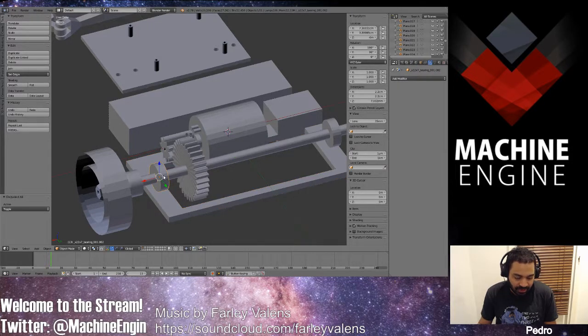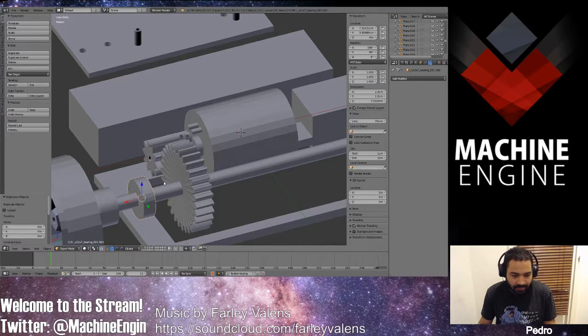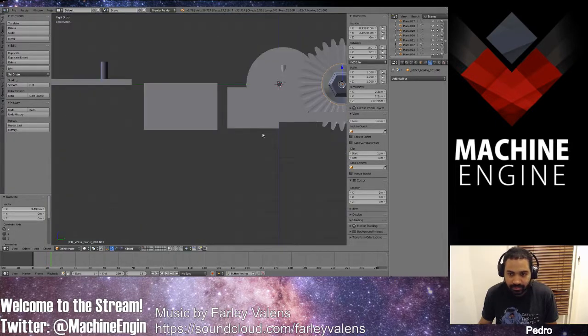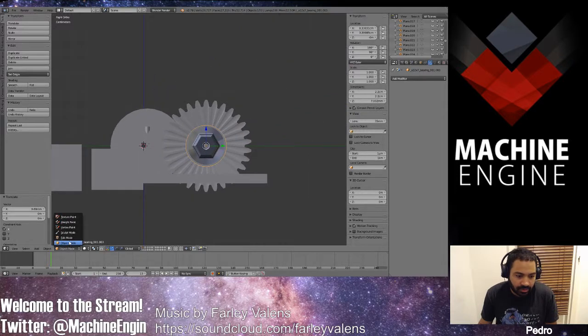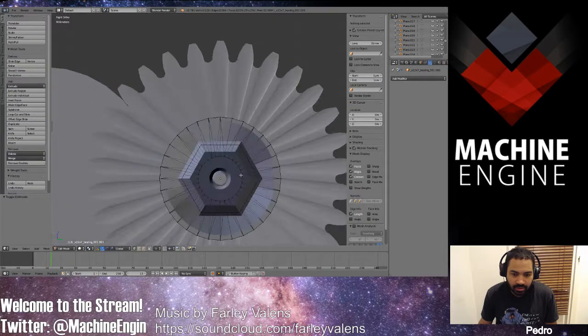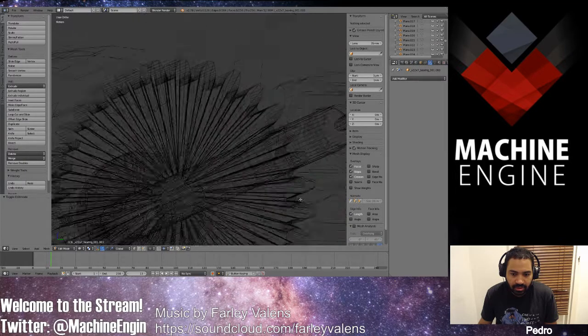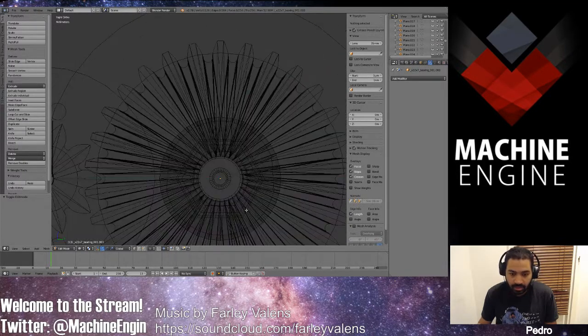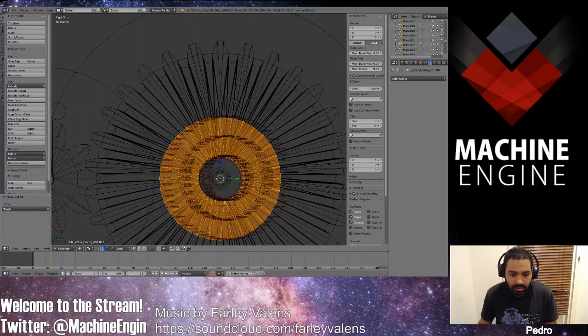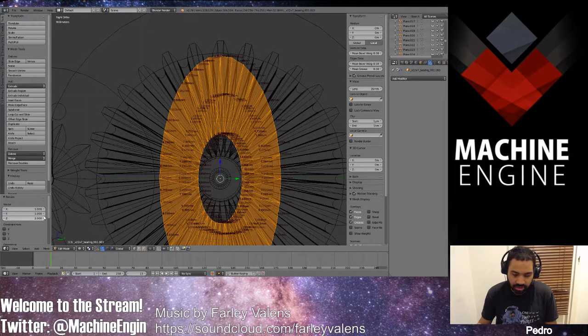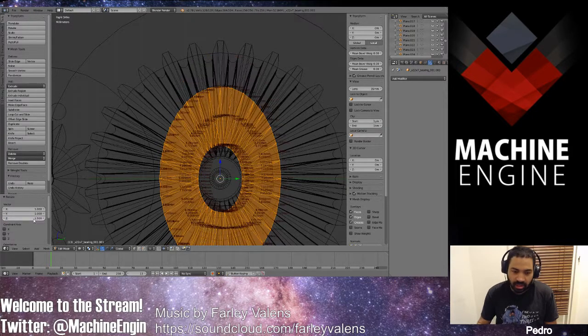I'll do this first. So what I do is copy, put it next to it. Let me wireframe it. Let me scale it on the Z twice. Ooh, that's too much. You gotta just try out some stuff. 1.5.